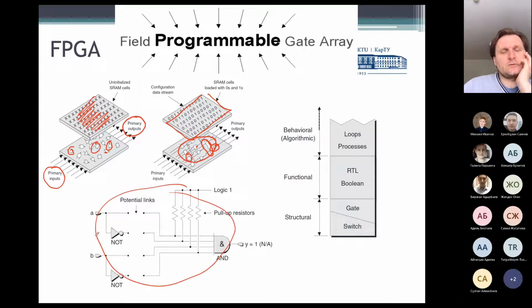That digital structure has two inputs, and we may put a mask, for example, one here and one here, and at the output we have the function Y equals A, not B. So using that mask, which can be represented by that field, we may program and make a new digital function.